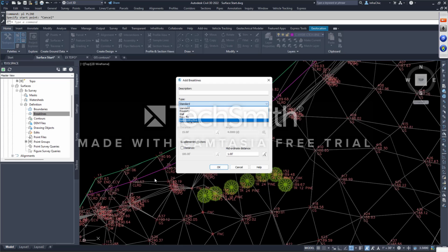So you have to be careful when doing walls. Depending on how the surveyor shot the shots, if the surveyor was actually at the base of the wall and shot the toe of the wall, then you could get away with saying that this break line is the toe and it's a 4-foot tall wall. And it would take every shot here along this break line that it sees and then would add 4 feet and slightly offset it in the surface.